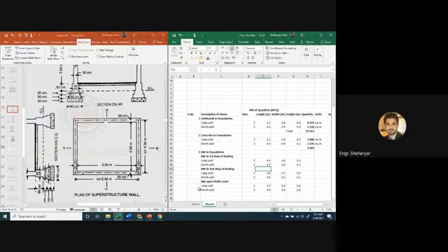So look at now. Observe the lengths of the long walls and length of the short walls. For the most bottom layer, the length of long wall was 5.2. Then the above layer 4.9. Then 4.8. Then 4.7. Length of the short wall for most bottom layer is 4.4. Then it is 4.7. Then 4.8. And 4.9. As I told you that the length of the long wall will be decreasing and length of the short wall will be increasing.